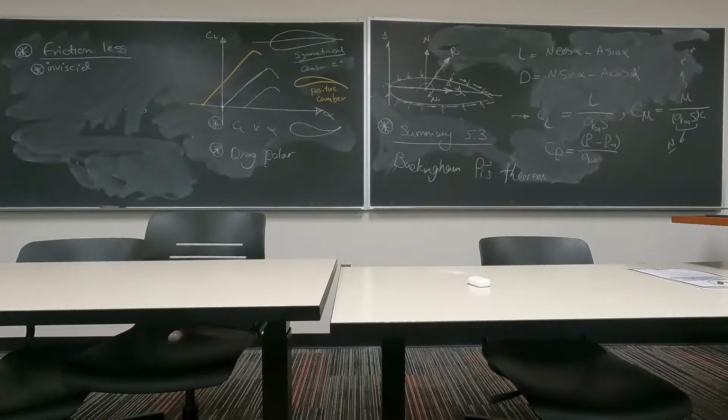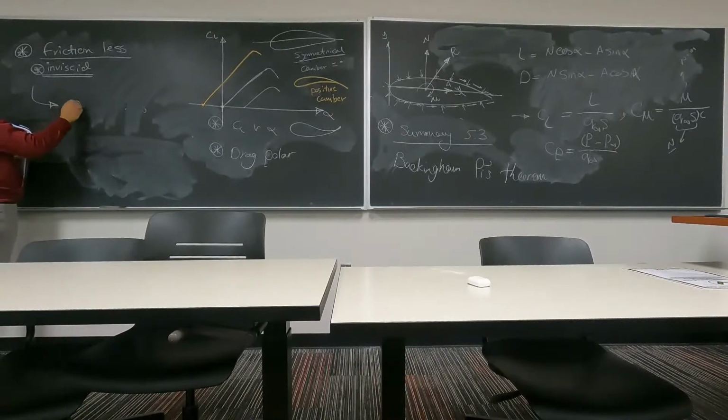The only problem we are going to face with this assumption is that we lose the ability to calculate the friction drag, and the pressure drag calculations are going to be very inaccurate, right? Okay. So this essentially means your forces are only a function of your pressure.